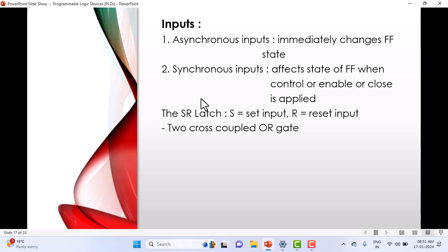When I say timing analysis is very important from the industry point of view, you can't learn it just by reading the book. You should take real circuits, for example flip-flops, shift registers, counters, and do timing analysis on that, specifically static timing analysis.